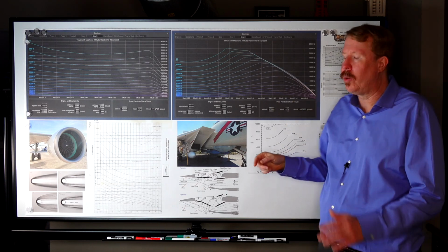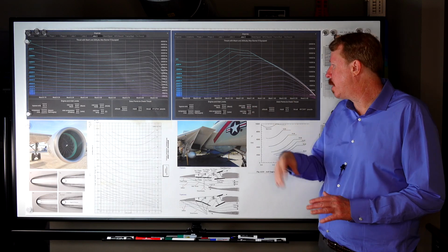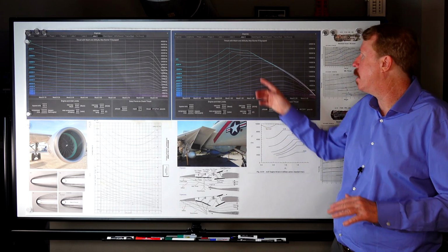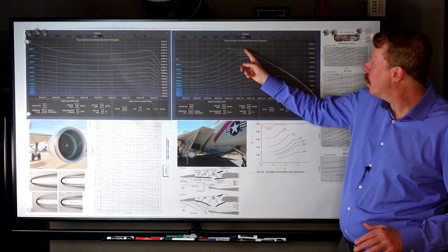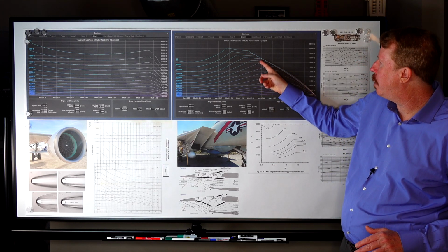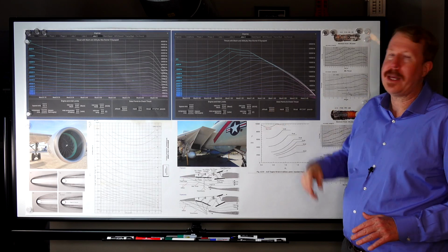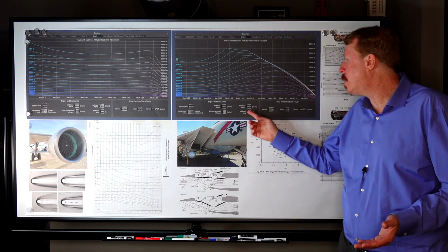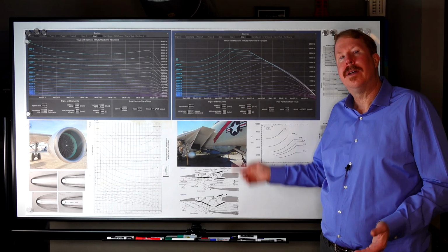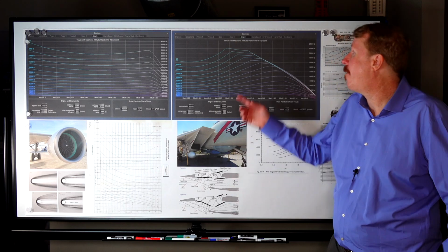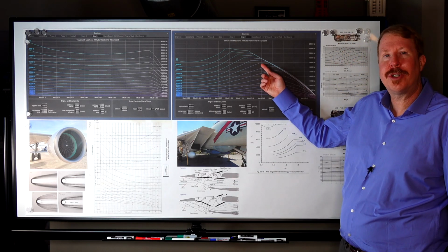And what's kind of cool is, while in this case we put 630 knots equivalent airspeed as the maximum dynamic pressure this engine is allowed to deal with, the higher you go into thinner air, the higher a Mach number you can get to before you hit that pressure limit. Why? Well, this is a pressure limit in the inlet. The higher you go, the thinner the air gets. And so the thinner the air gets, the faster you can go without hitting the pressure limit.